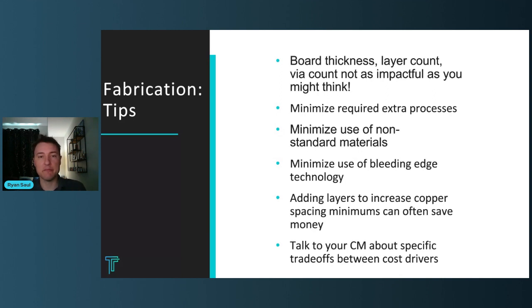Designs that have via in pad, meaning you are drilling your vias into solderable surfaces that will require components added to them. Well, that's fair. Then epoxy filling and plating over those vias absolutely makes sense. It may even save costs on the back end. But if you don't have this, you just have bog standard, dog bone style vias on your signals, then don't do this. It's a waste of money.